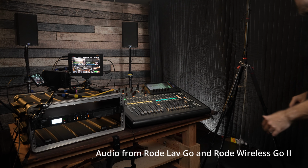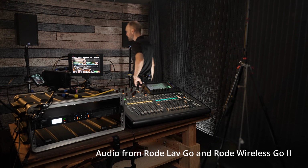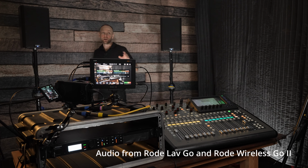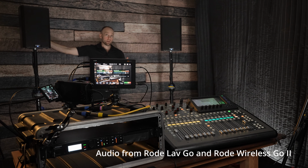We'll walk over to our speakers and turn them up. Now, granted, I have to be a little bit careful since I'm wearing the mic and I'm in front of the speakers. It's where it's good to have someone else talking and someone else turning up the speakers. And this little bit of legwork is sometimes necessary to set your overall gain for the room.